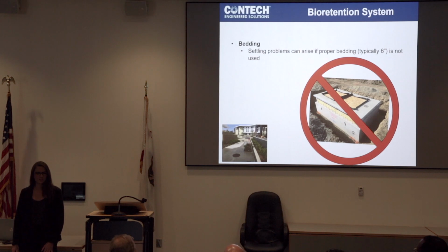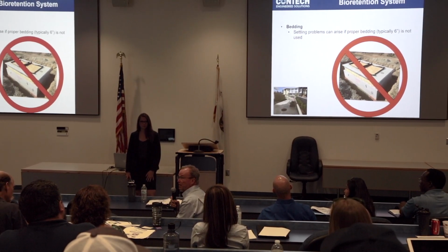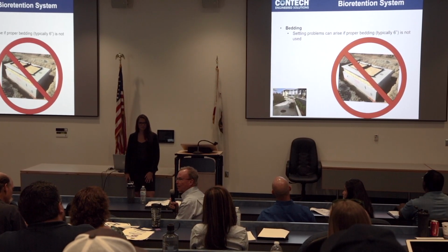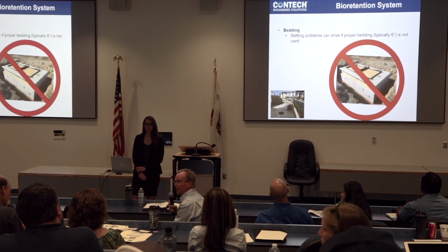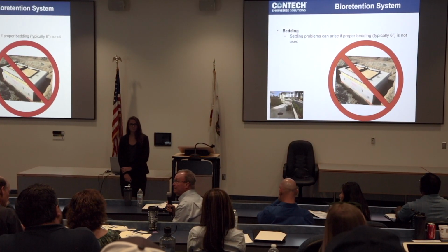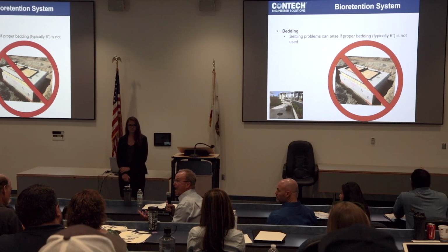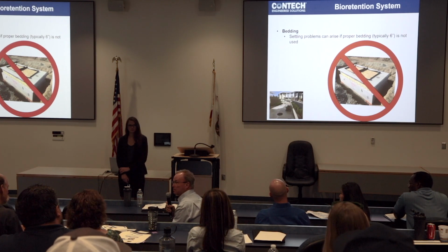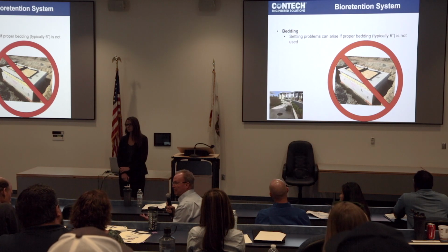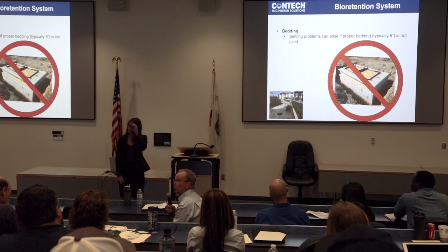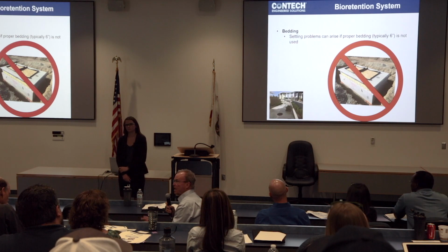Mark, would you like to follow up with that question? It was placed on native. Placed on native, yes, and at that point, it does look great, and that's a real key to all of this, is that things can look great until they get backfilled, and it's during the backfilling that all of a sudden differential settlement can occur, and you don't see it, and next thing you know, you've got a system that leaks. So, yeah, that is a very valid point. Things look good unburied, and knowing ahead of time this is what needs to happen is very important.